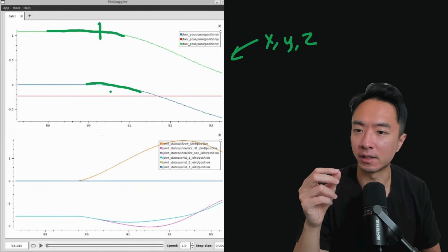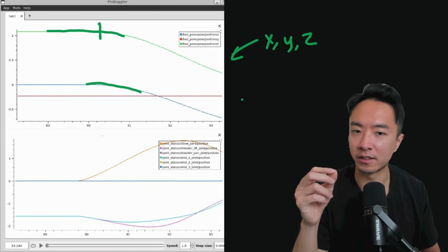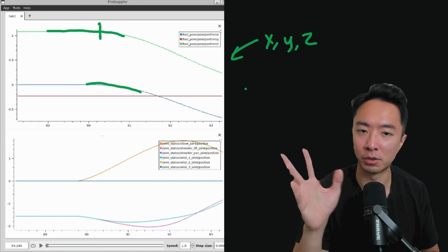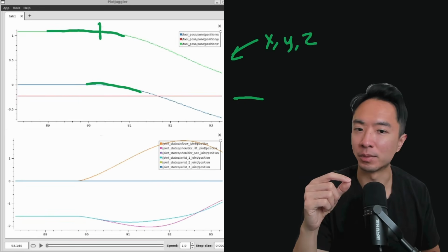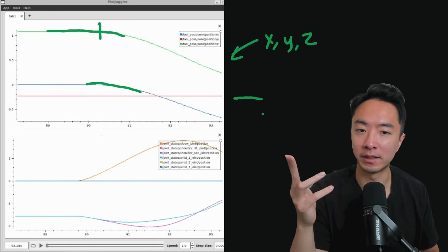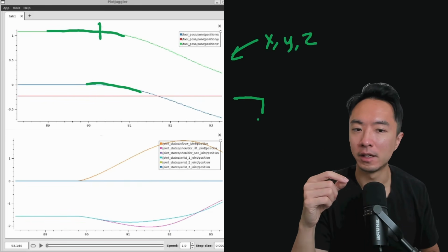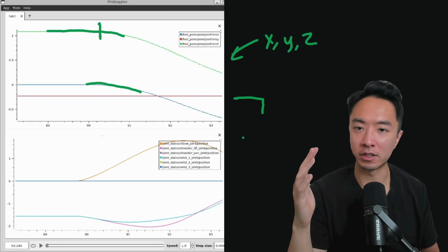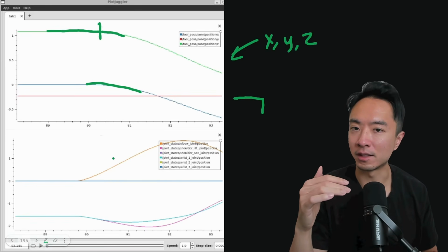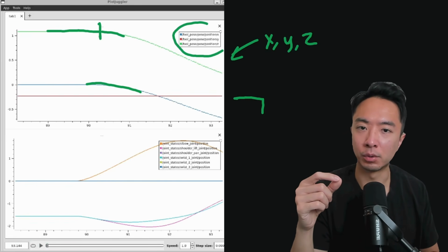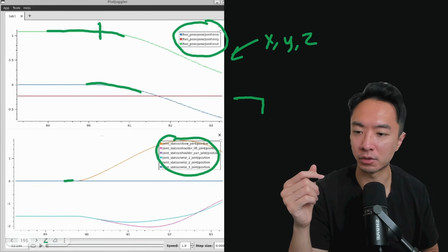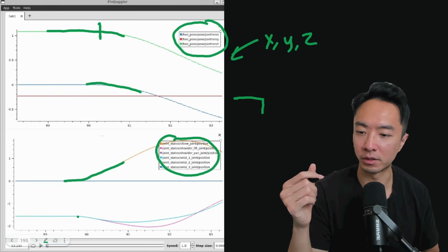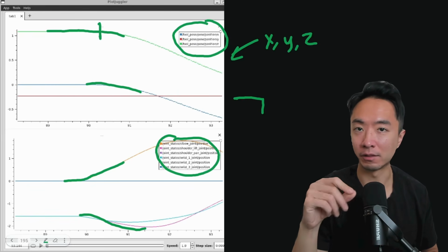You can also see that there are no sudden jumps, because if you didn't do this whole LERP and SLERP, what's going to end up happening is, let's say your initial position was at 0 and then you commanded a new pose, then you're going to see a sudden jump down to a different position. It's going to be a step change instead of a gradual change. You could see it's being reflected in both the tool end position as well as the individual joints, because you could see these joints are also very smooth and gradual. So there are no sudden jumps for any of these trajectories.